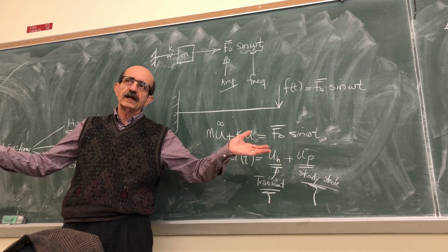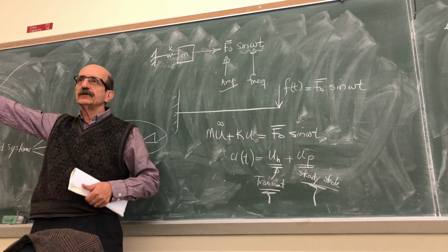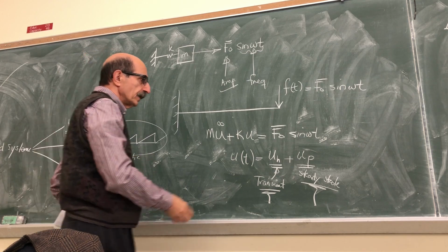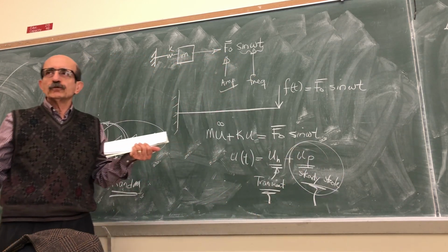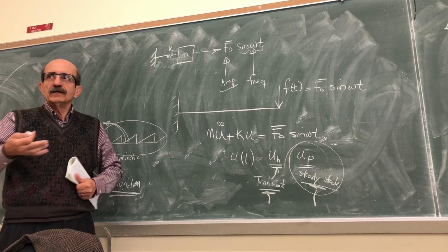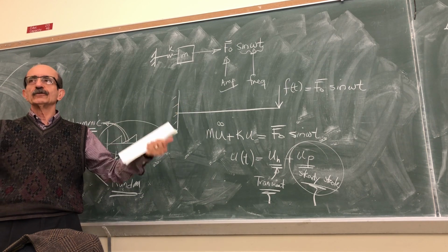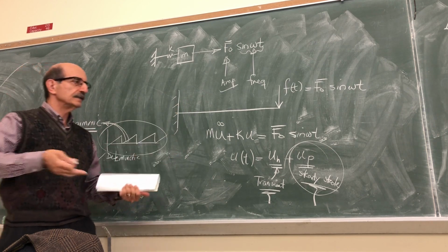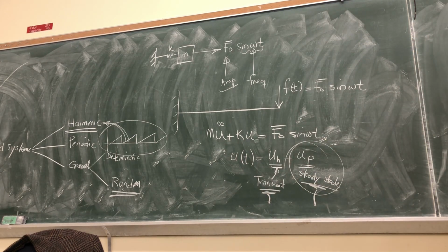So it's transient, it disappears. You have an underdamped system, it decays with time. However, this part depends on the action of the forcing function. If the forcing is there, you will have that vibration ongoing as long as the force is there. That's what we call a steady state. But we'll see other reasons that we call those that way later.